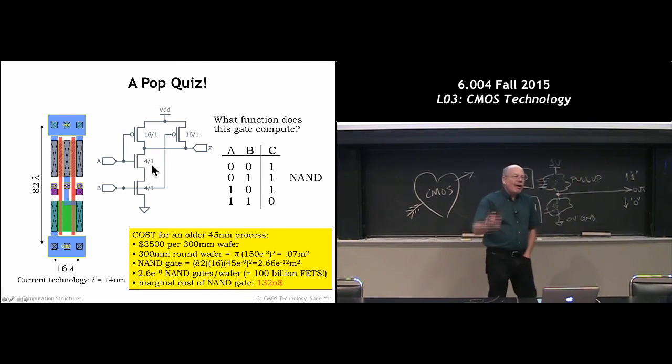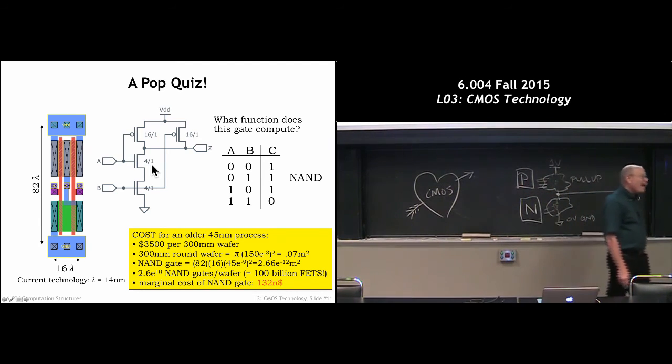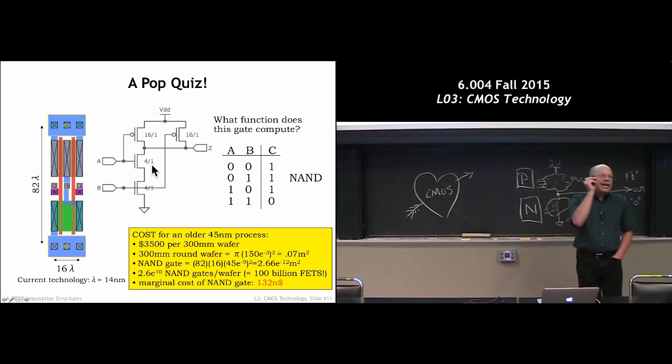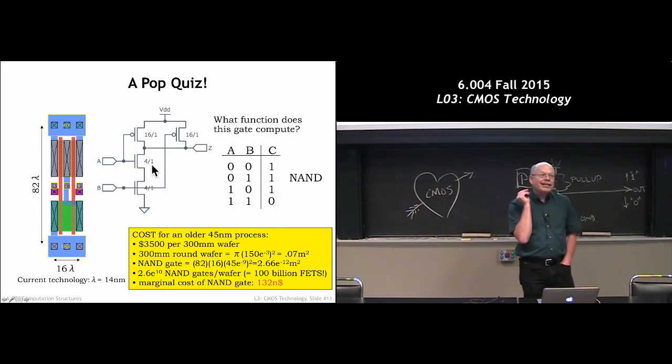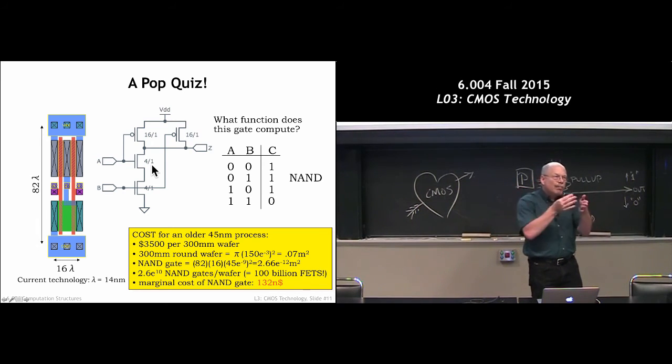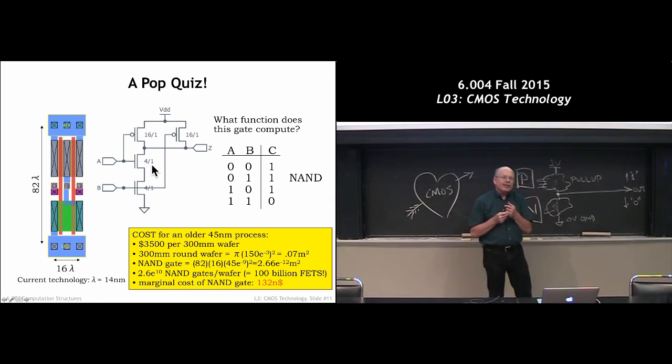The reason that you all own umpteen gigahertz processors is that they're made of logic gates. Okay, 1 gigahertz corresponds to a 1 nanosecond cycle time. So we're talking about logic gates that are thousandths or a hundredth of that cycle time. So these are very fast, very small devices. And those are related, right? Because if they're small, the capacitance is small. That means that we can change the node voltages very, very quickly. So 10 picoseconds, right? So cheap, small, fast. This is like perfect. I'm in love again.